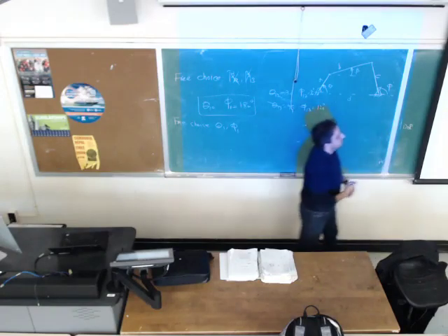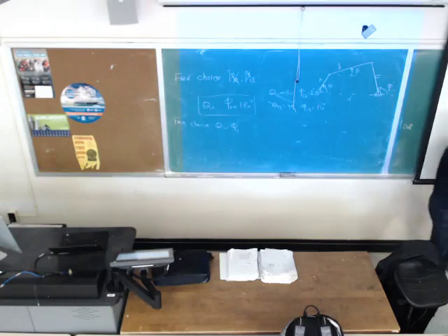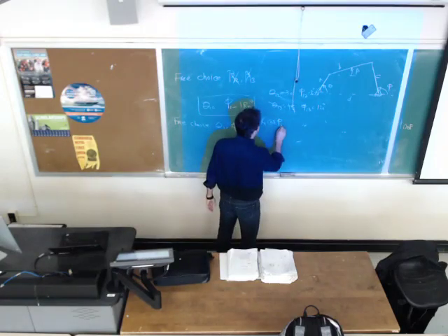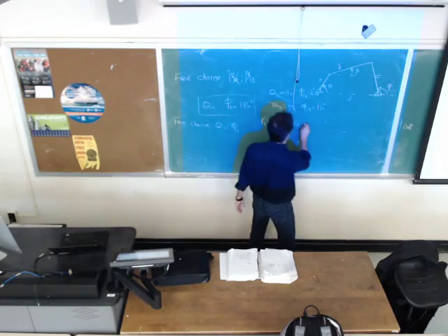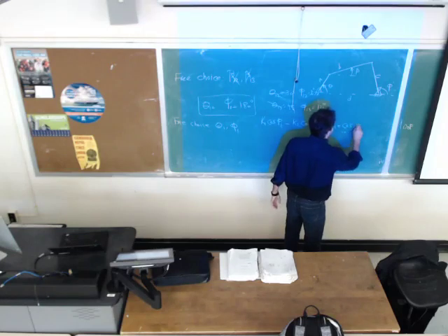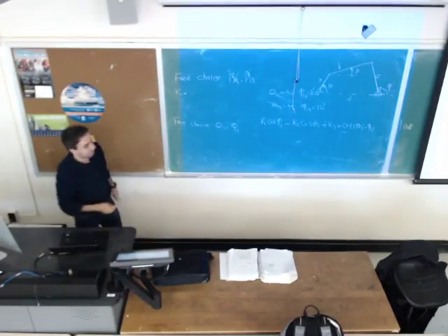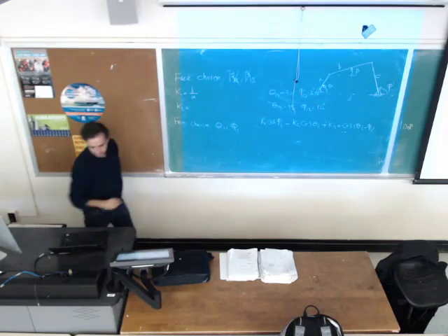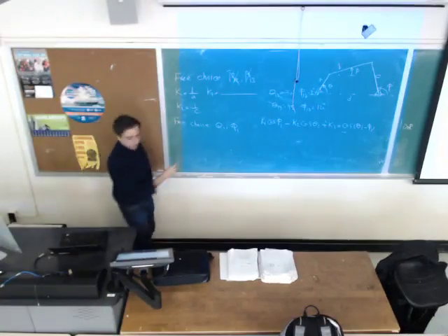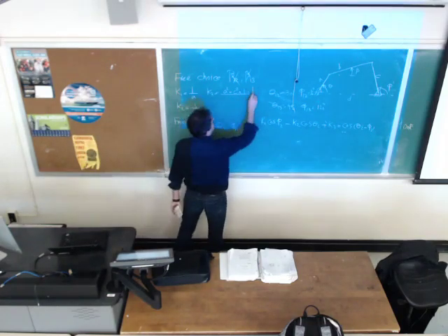when we did the 4-bar mechanism analysis, we could get this equation. We worked on that, and we ended up with this equation. We call it the Freudenstein equation. So K1 cosine of Pi minus K2 cosine of theta I plus K3 equals cosine of theta I minus Pi. And K1 is B over A, which is 1 over A. K2 is D over C, which is 1 over C. And K3 is A squared plus C squared plus 1 minus B squared over 2AC.